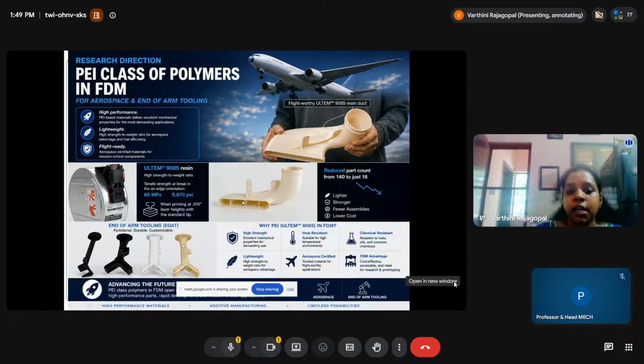Okay, the cutting guide is actually patient specific, so it's of one-time use. So you don't require any complicated cuts, because if you're going to use it multiple times, it should pass through the sterilization process. Okay, sterilization cycle. These thermoplastics might be difficult to pass through the sterilization cycles. So this is a one-time product. You can actually use PLA, high temperature PLA or nylon.